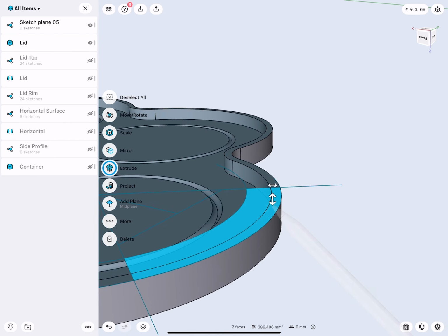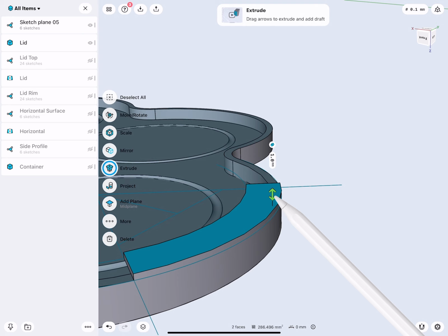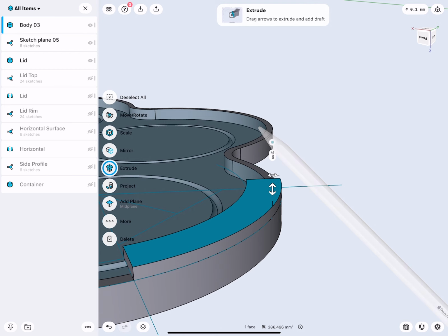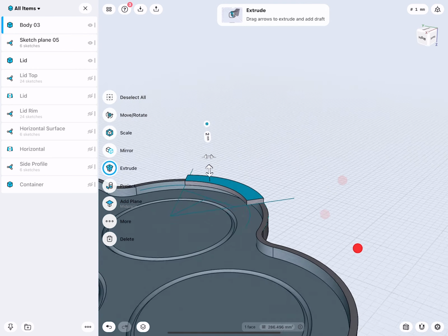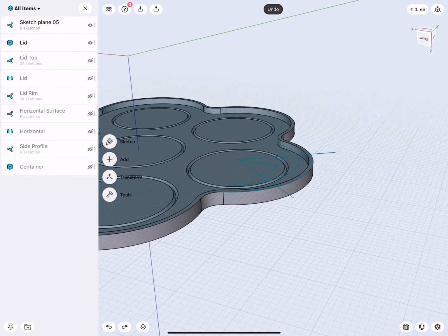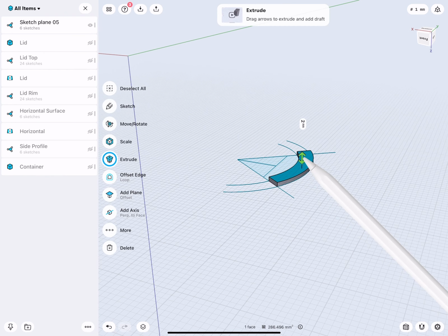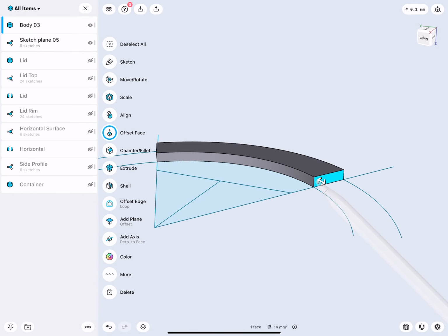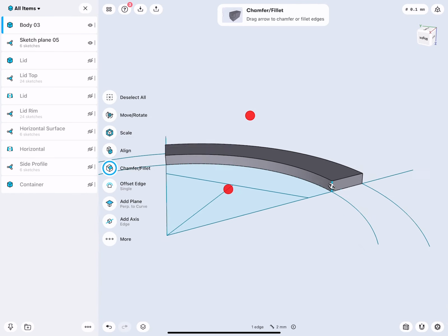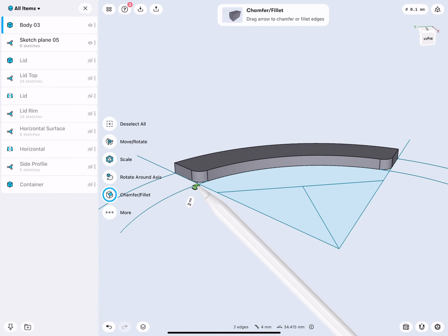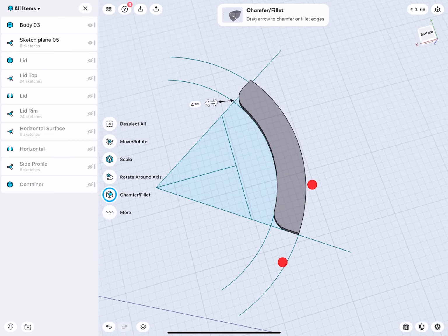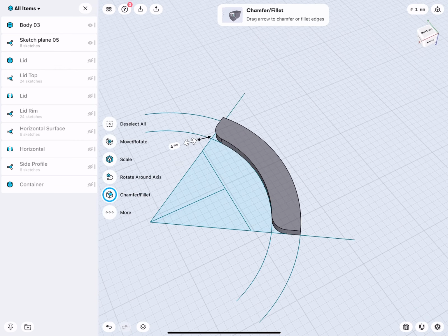So here, this part, we extrude up by 2 millimeters, and we want this to be a new body. This is important. So ideally, to maybe make this easier, simply extrude this up without seeing any object. Then we can go to there and there and actually give this a fillet like this, maybe a little bit more, like 4. Very good. So this is actually quite nice.